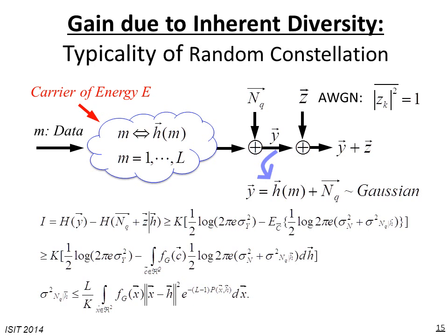At the end of the day, we will be able to write some expressions and bounds for the mutual information, and as you see here, I have an expected value in the first expression. In the second term, I have an expected value over C. This expected value over C is the expected value over different realizations of the constellation. So my intention is to select one constellation with M points in 2K dimensions, K being the number of receive antennas, with IID Gaussian components, apply random coding with uniform distribution, selecting these constellation points to the resulting channel, and compute the capacity.